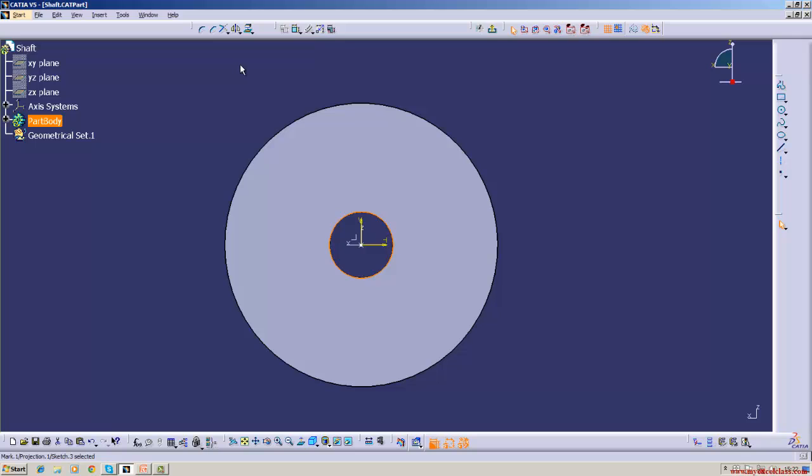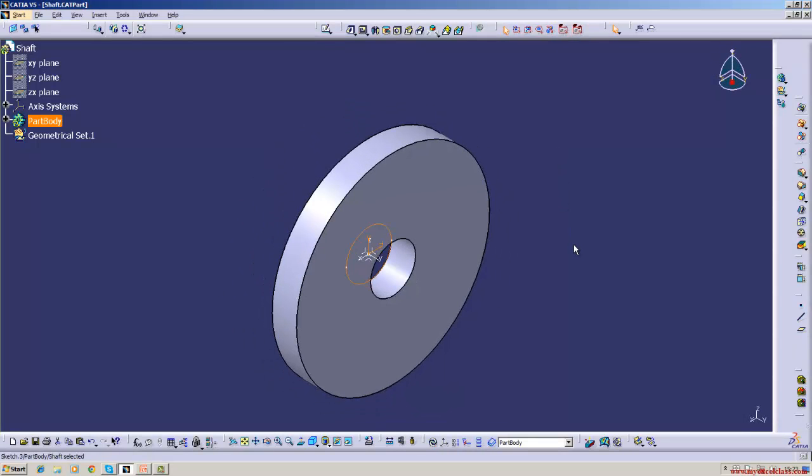Take the projection of that line, click, and then you have to create this line. This line is created, and then, last time we have done, no? Like this, you take the projection of that. The center is marked. And match with this. And come out of the sketcher plane.